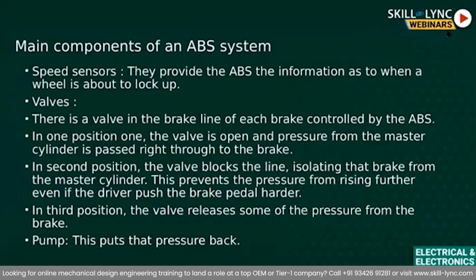This results in tires slowing down at the same rate as the car, with the brakes keeping the tires very near the point of braking at which the tires will start to lock up. This gives maximum braking power to the system. When the ABS system is in operation, you will feel a pulsing in the brake pedal. This comes from the rapid opening and closing of the valve. Some ABS systems can cycle up to 15 times per second. So I hope the concept of ABS is clear, and what is called cadence braking technique, which is the foundation of the ABS system.